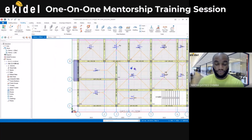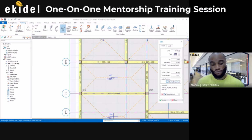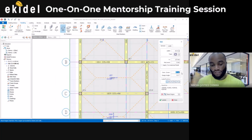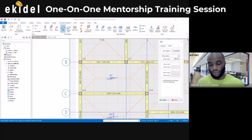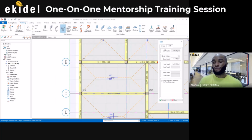To add a cantilever slab, can you hear me? Yes. Okay. To add a cantilever slab, you click on your slab the same way and define your depth. I think we use 127, then the concrete cover 25, and then for the loads we choose 1.77, and here we use this. Now, once you've done this, come back to your general.